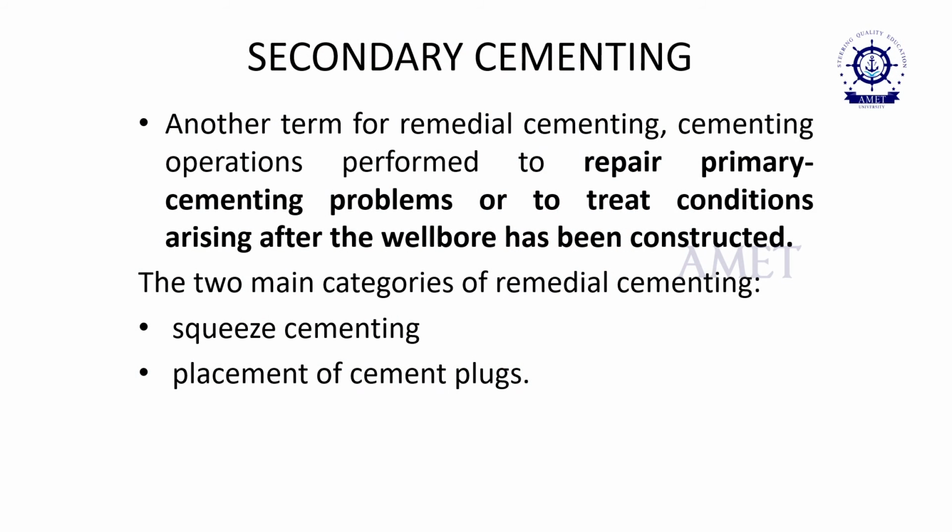Now we have the doubt, in some formations we may be dealing with other lithological properties which may create a weaker bond in the cementing, or the cementing cannot be completed in some interval. For that, we cannot go with primary cementing again, because the annular space is already filled completely with cement and it is settled, it becomes solid.